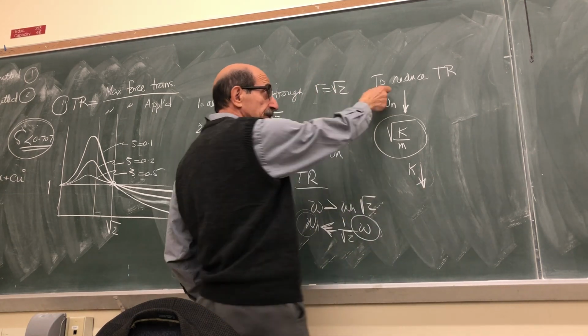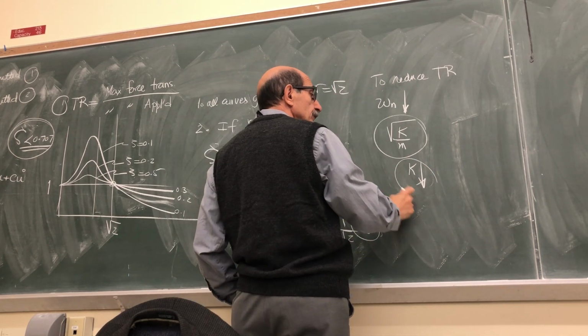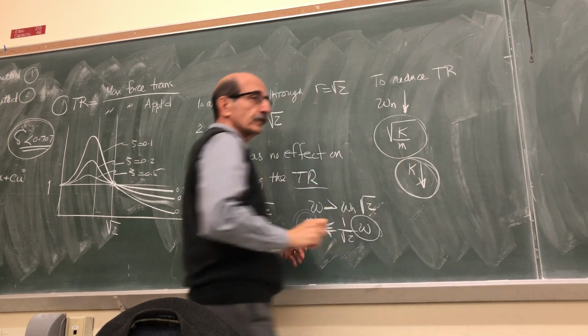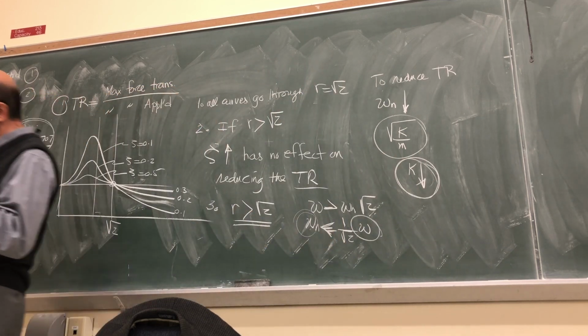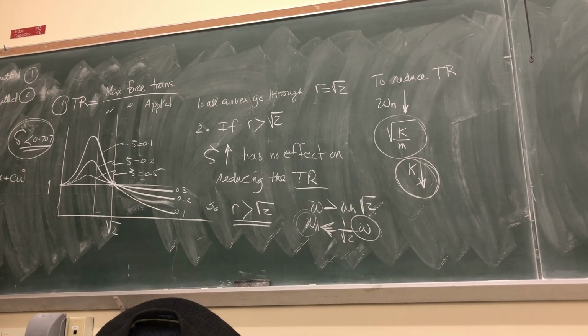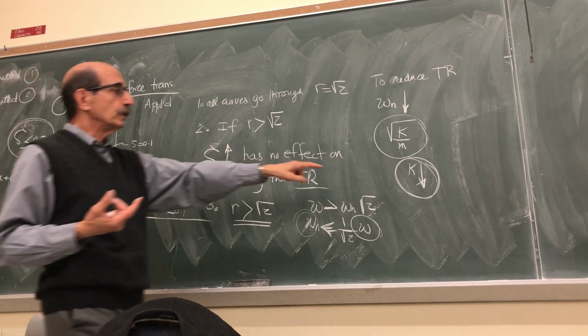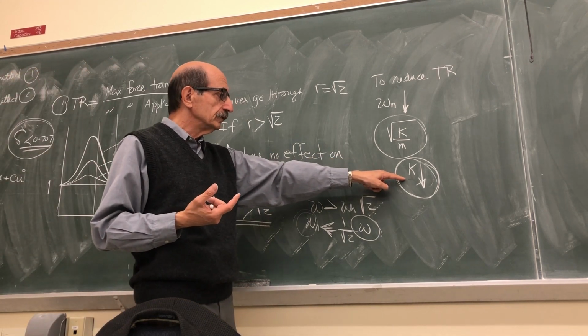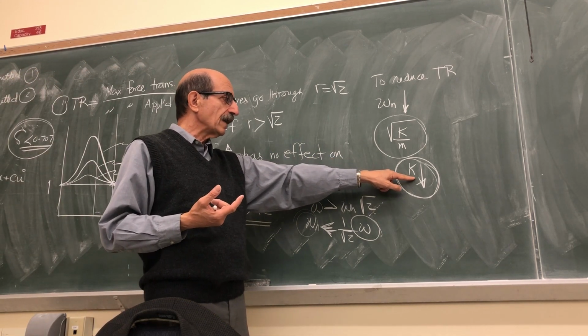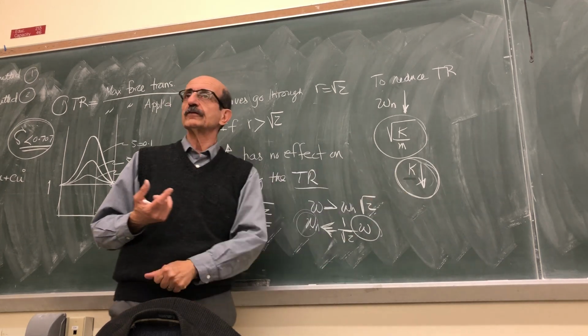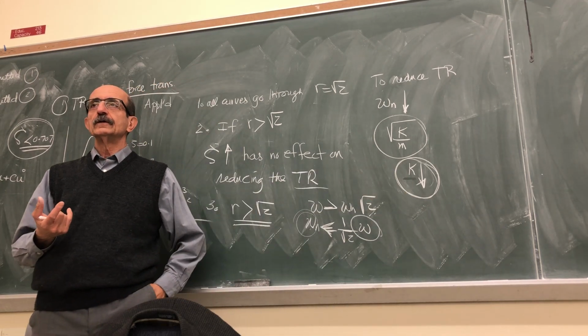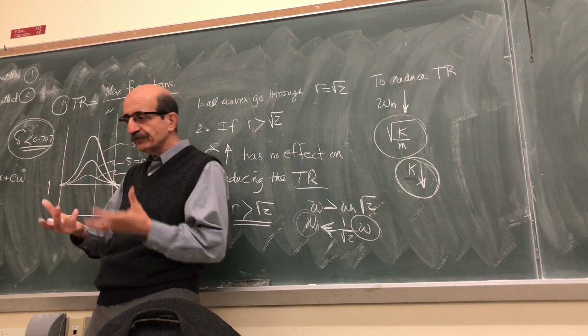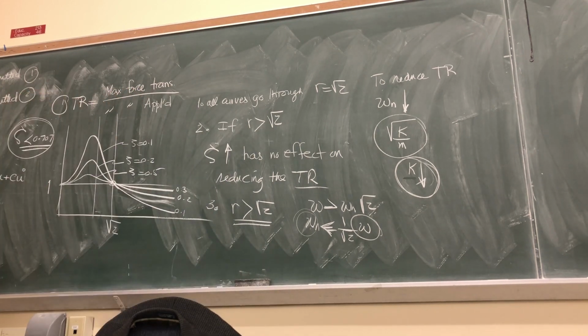So the most effective isolation system, the most effective stiffness for the system that would reduce the transmissibility ratio, is when you have a soft stiffness, or as small of a stiffness as possible. So a soft system is the best system for vibration isolation.